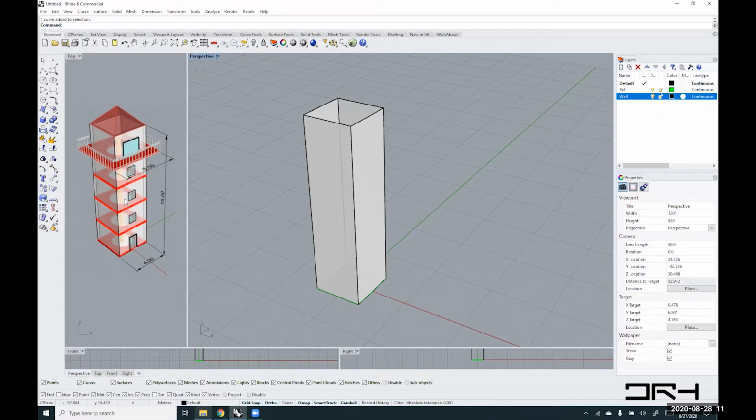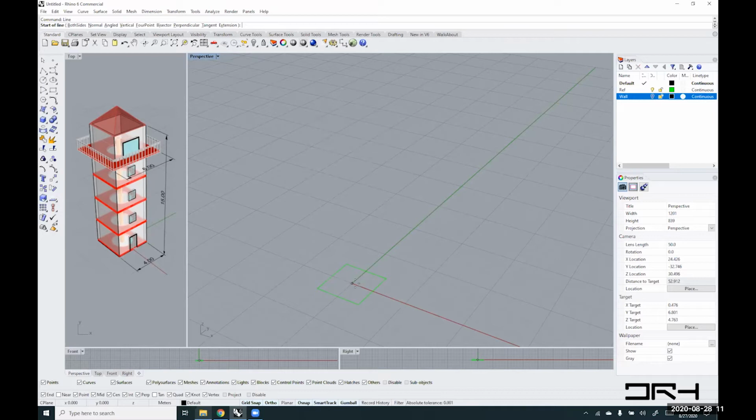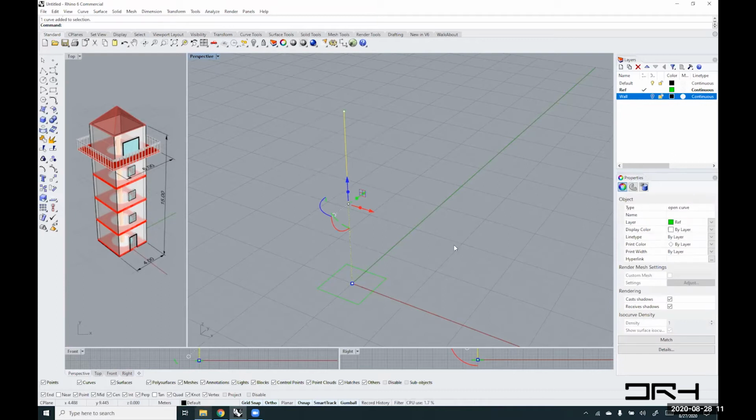So now that I created my wall and the height is 15 meters, what I want to create is basically the floors. I will hide my wall for now, and I need maybe more reference points. Perhaps you don't need it, but I'll do it as a good practice. I'll create a line down from the bottom here, and remember to choose vertical. So I will go from the center and vertically 15, and that's going to be the end of my line. I should have chosen to work within the reference layer, and this way I don't have to keep selecting and moving to the reference.